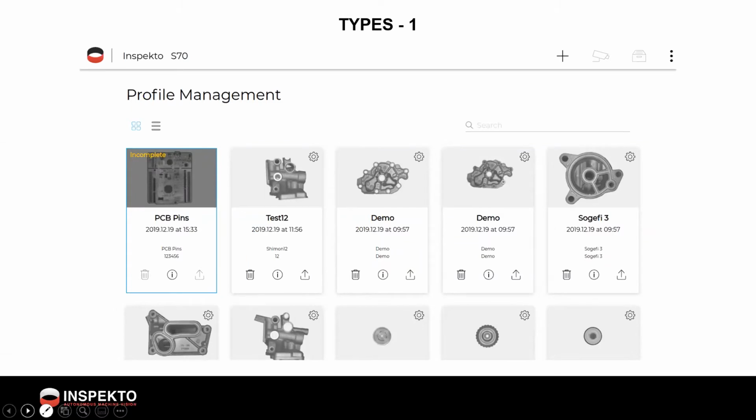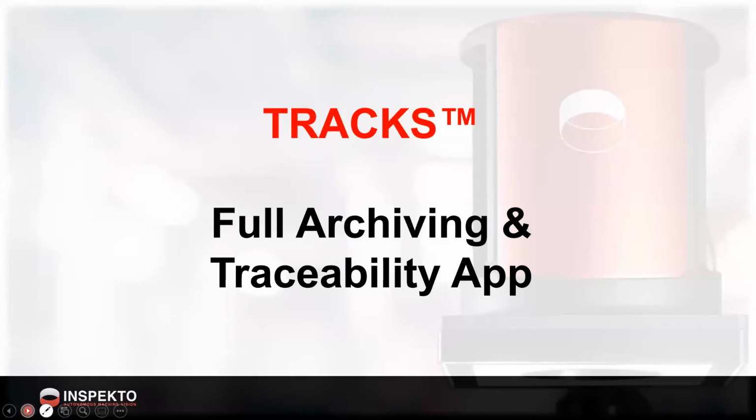You can program unlimited different profiles, and you can swap between them manually, or you can have your PLC swap between them. So now, as long as the PLC knows what you're making that day, part of the changeover can be telling the camera, hey, this is what product we're running right now, either for the shift or maybe just for the next 3 parts. And the system can get the directive from the PLC to swap profiles and record accordingly.